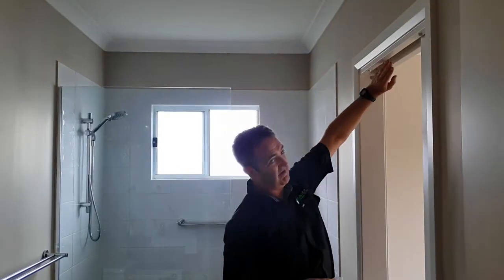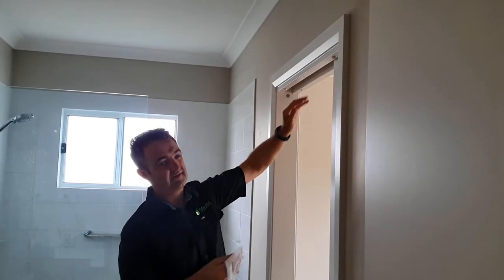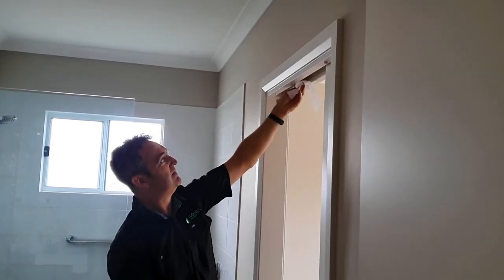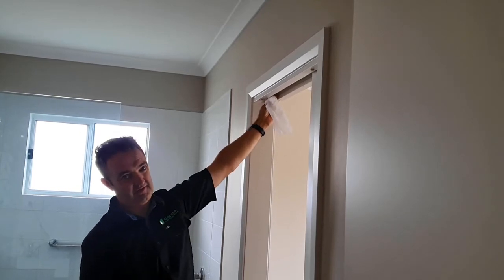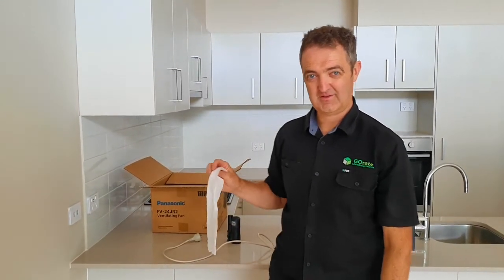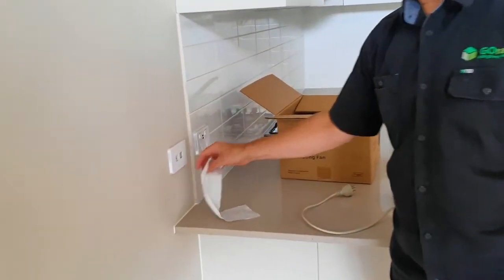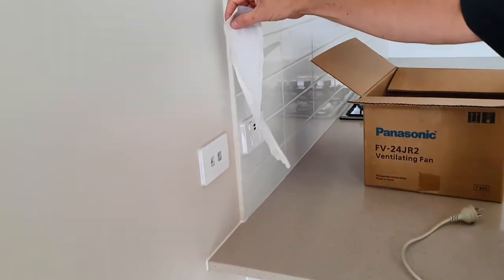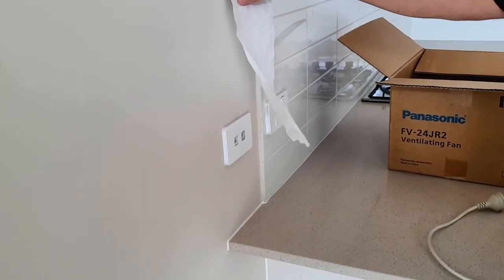We have another cavity sliding door connecting an ensuite to a bedroom, and quite a bit of air leakage through there as well. Another point of air leakage that we don't often think about and we think is pretty trivial are actually power points and any data entry through. You can see here, basically we've got wind whistling through.